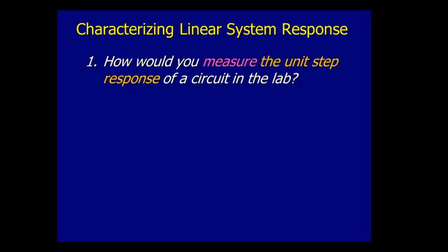Make it DC? Well, I want a step. I need a step to initiate it. What's the other knob I can affect on a rectangle wave? Duty cycle. Set the duty cycle some high percent, like 80% or 75%. Then my square wave lasts, my on time lasts a really long time.